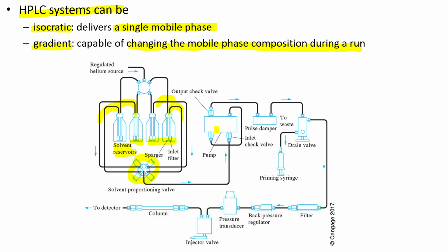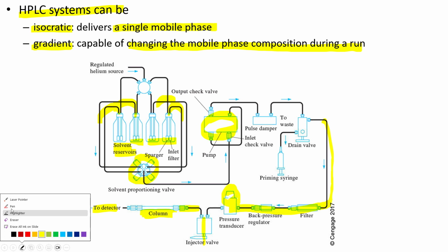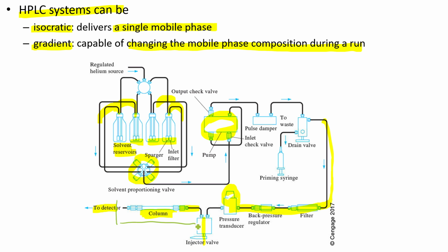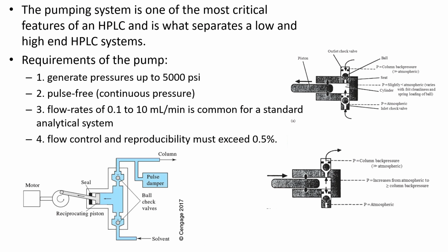It takes those things and it has a pump that creates that at a high pressure, and then it mixes it, and then it takes this fluid and it runs it through at a constant pressure, and it monitors the pressure for it, and it goes through an injection valve where we introduce the sample, and then it's carried onto the column, and it goes into the detector. And because this, again, is chromatography, it's a thermodynamic process, typically you're going to do this in a temp-controlled environment. All right, so even if it's ambient temperature, we want it to be a constant temperature in the system.